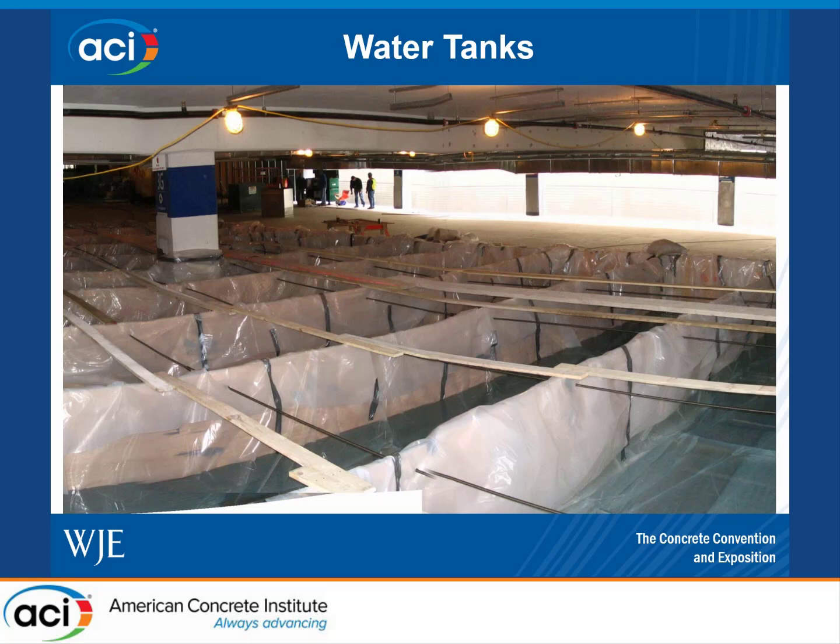The key is the water tanks can't leak. You need a uniform water level throughout the test. And here you can see there's multiple bulkheads installed to subdivide the areas to address floor slope to make sure that you have a uniform load across your test area. You need to make sure the bulkheads are strong enough to sustain the load and avoid any blowouts during the test, which has happened.